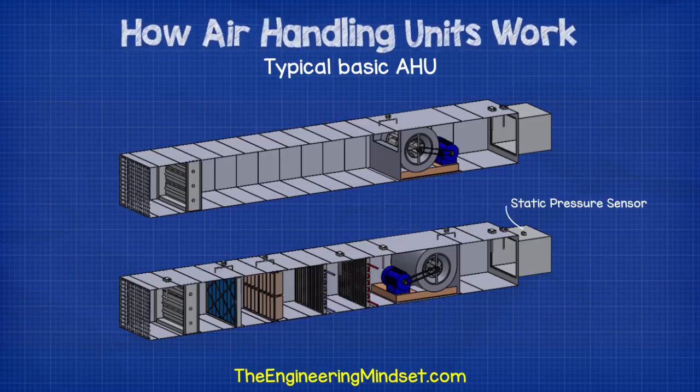We'll also likely have a duct pressure sensor shortly after the fan. This will read the static pressure, and in some AHUs, the speed of the fan is controlled as a result of the pressure in the duct. So we'll also very often find a variable speed drive connected to the fan for variable volume systems.